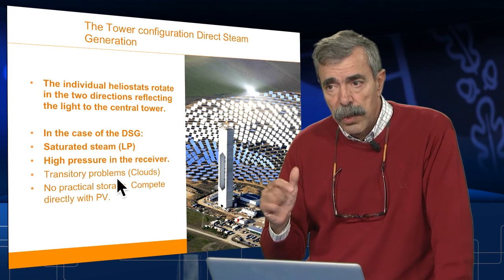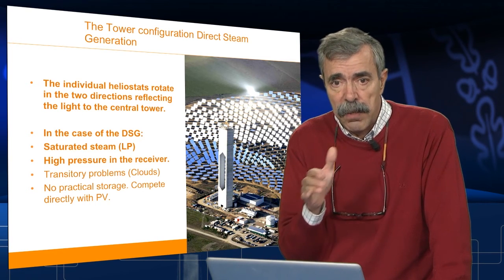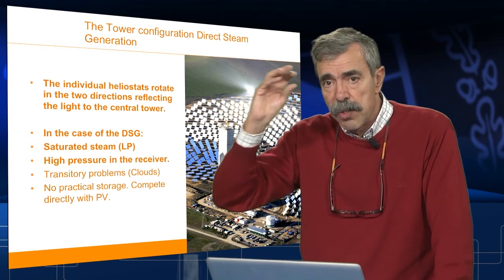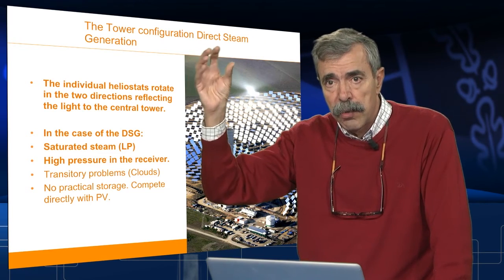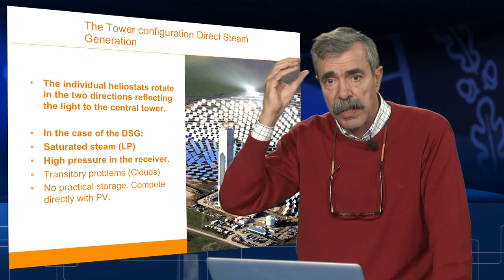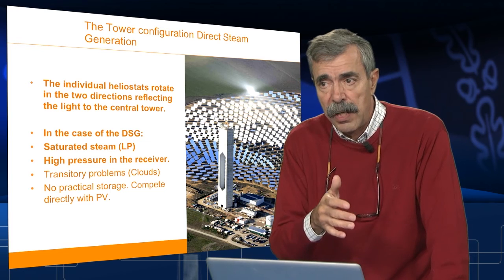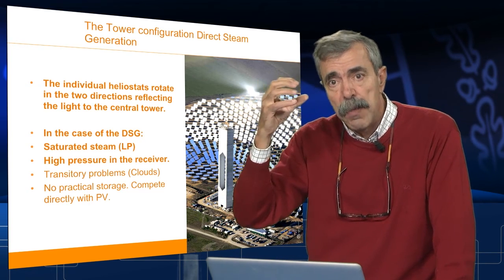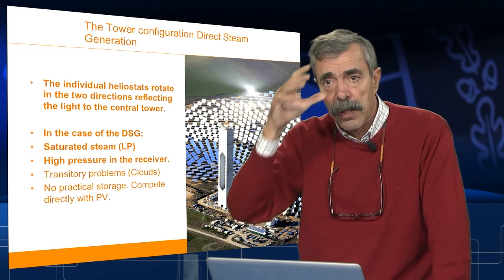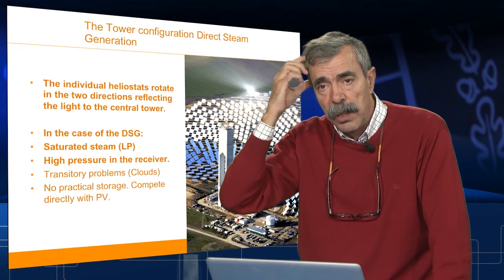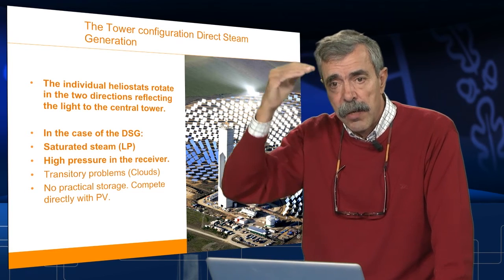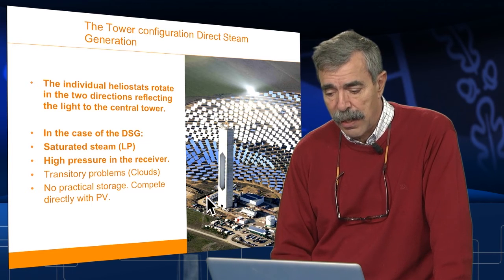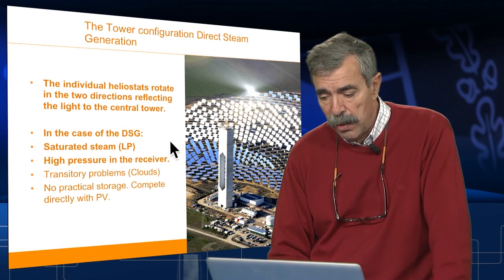Not to mention when this happens not just at the expected moments, but because there is a cloud moving on the horizon and you don't know exactly if it is going to affect you or not. In the middle of the day, the stress that can be produced just because suddenly a cloud removes the energy and reduces the temperature of the receiver has a relevant effect on the durability of the receiver.